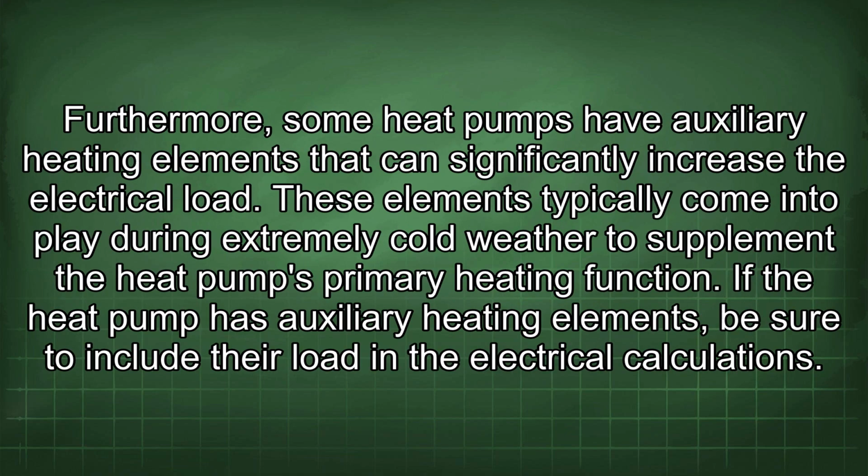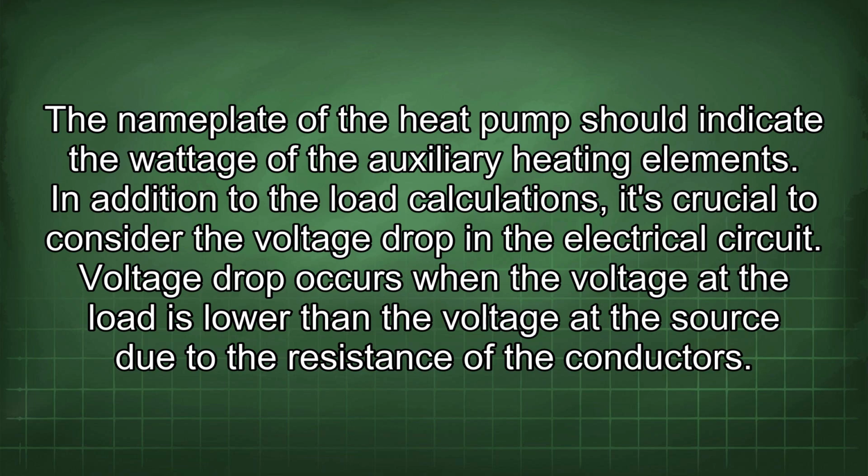Furthermore, some heat pumps have auxiliary heating elements that can significantly increase the electrical load. These elements typically come into play during extremely cold weather to supplement the heat pump's primary heating function. If the heat pump has auxiliary heating elements, be sure to include their load in the electrical calculations. The nameplate of the heat pump should indicate the wattage of the auxiliary heating elements.